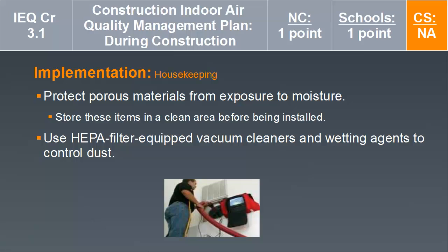Implementation of the housekeeping section of the SMACNA guideline. You need to protect porous materials from exposure to moisture. Store these items in a clean area before install. And use HEPA filter equipment, vacuum cleaners, and wetting agents to control dust.